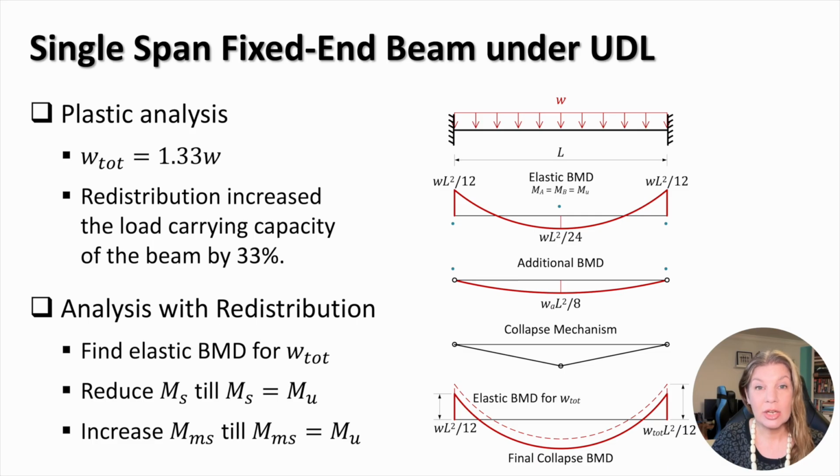In the second stage, a hinge developed at midspan, changing the structural model into a mechanism. The plastic structural analysis can become very long for structural models with a high order of static indeterminacy. An alternative method for calculating bending moments is based on the elastic structural analysis, followed by the redistribution of moments.